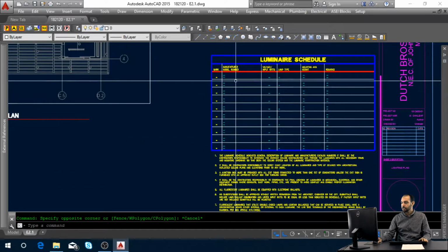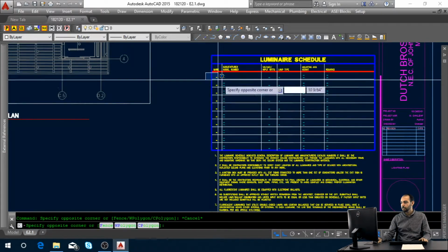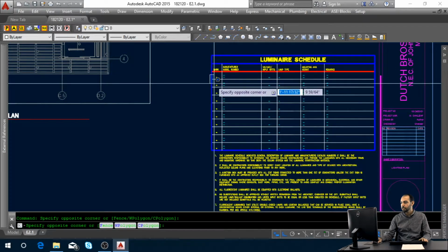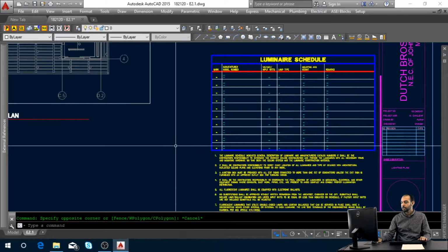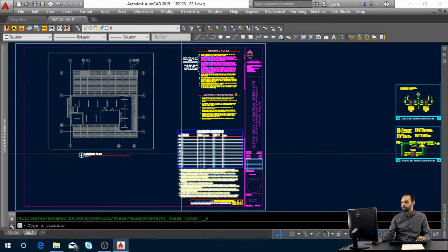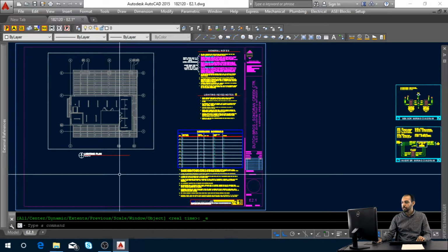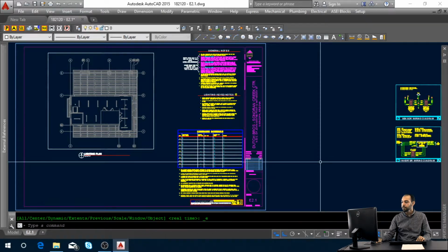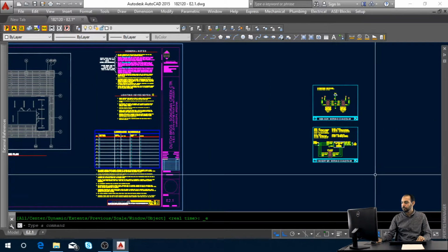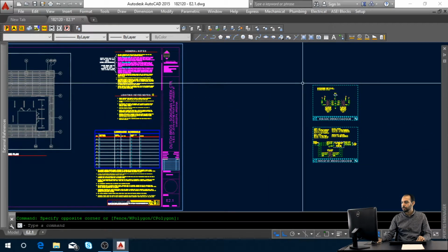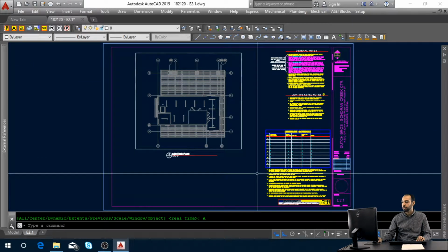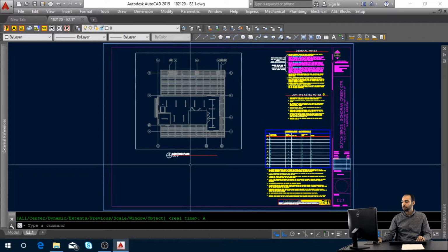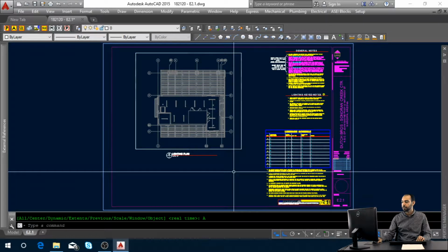The purpose of this is to indicate what each light is going to be. You're going to tag the light fixtures and you're going to select the model numbers, the manufacturers. You'll put the voltage and all that information. And that's again later on. For now, we can leave it blank and you'll work with your designer to help you figure that out. These over here, we can delete these. And if you're not sure, you can verify with your designer and leave them there until they bring clarification. So this is all you need to do for your lighting plan.